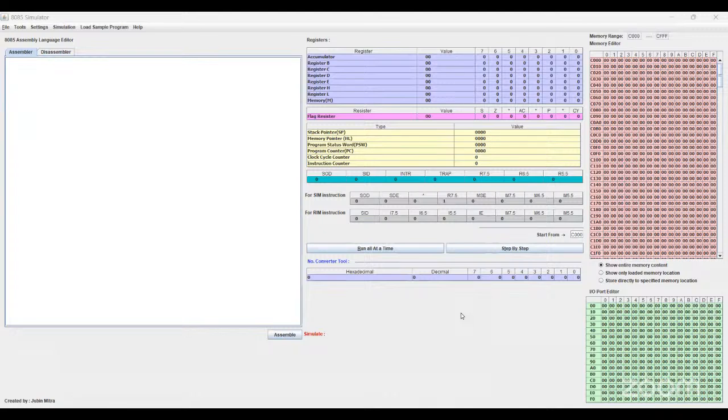Then complement the accumulator: whatever the contents, ones will become 0 and zeros will become 1 in the accumulator contents. Then complement the carry flag: zero will become 1 and 1 becomes 0. Then we can set the carry by the STC instruction.